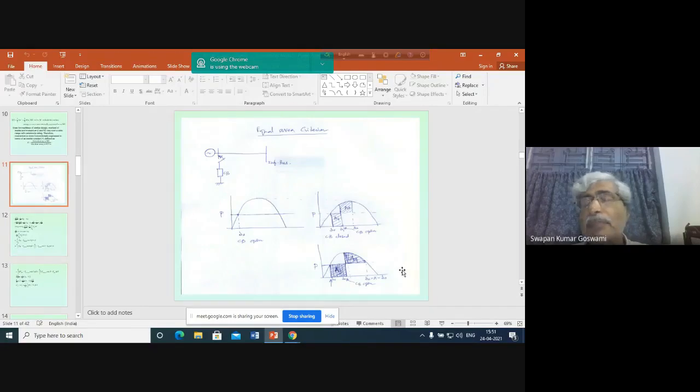So it indicates that the opening of the circuit breaker has to be completed at or before this point is reached, and this point is indicated by this angle delta CR, delta critical. Why do we call this angle critical? Because this is a very important angle. If the circuit breaker is not opened before this point is reached, then the synchronism of the system cannot be maintained, and stability of the system will be lost. That's why it is called the critical angle, or the critical clearing angle.